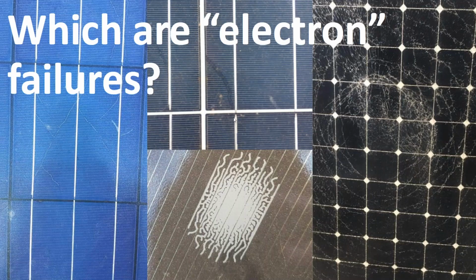Okay, so here's some module failures, and now we should be able to understand which is which. So this failure on the right is a shipping issue where a package of heavy weight is put down on the very top module on a pallet of modules, and that is not good for it. That can break it. So you need to make sure you're giving your solar panels a good visual inspection as the shipments arrive. And that's another reason to do projects by the pallet, so that you don't have to unpack the pallets and even do shipment to site if that suits your business size.